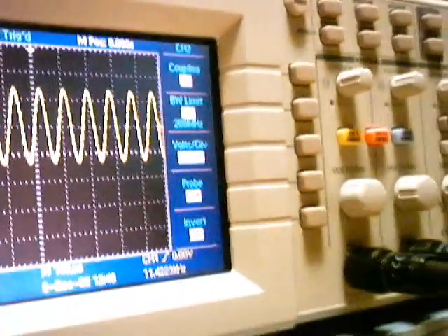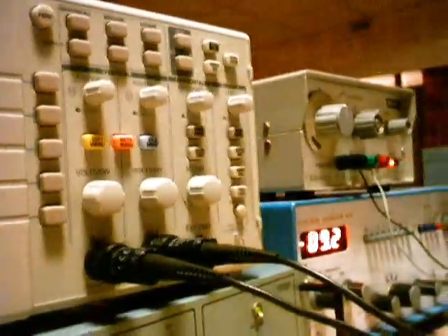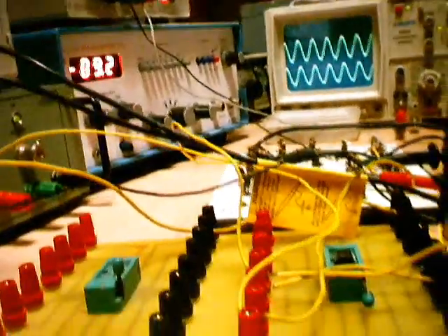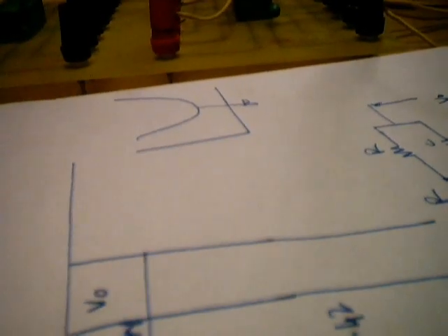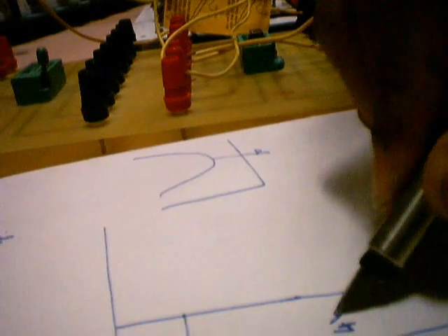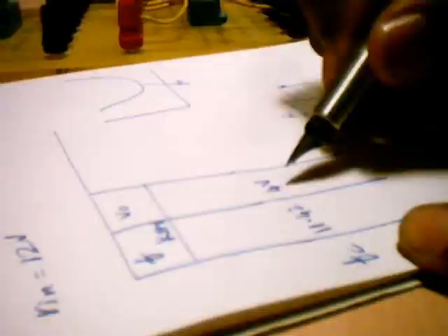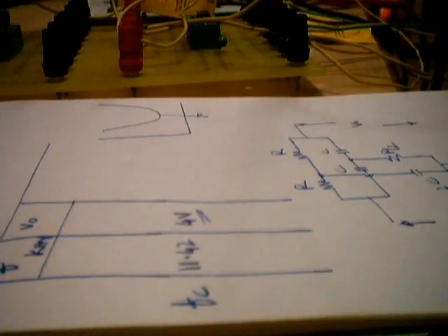So we can have one of the readings of your narrow band stop filter at FC. It is 11.42, this is in kilohertz. My output voltage happens to be 2 into 4 volts. So this is totally 2 into 2 divisions, 4 volts. The input voltage was at 12 volts. You can say this is the output voltage. So we noted this particular position.